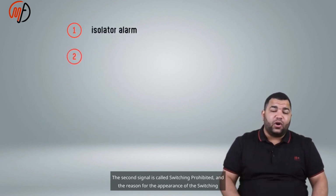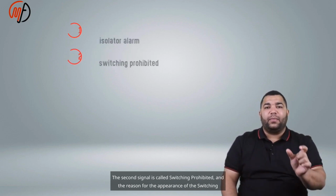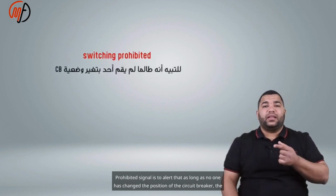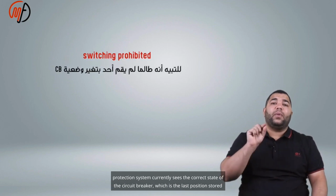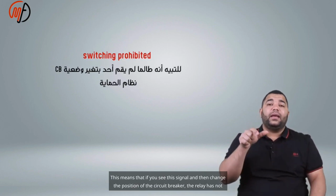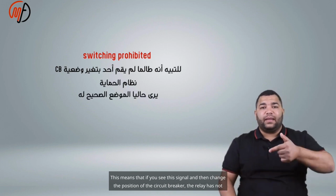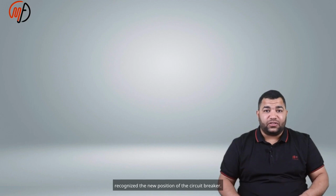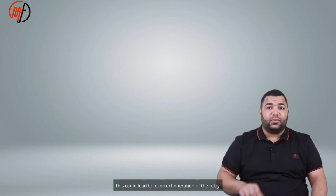The second signal is called switching prohibited, and the reason for its appearance is to alert that as long as no one has changed the position of the circuit breaker, the protection system currently sees the correct state of the circuit breaker, which is the last position stored in it. This means that if you see this signal and then change the position of the circuit breaker, the relay has not recognized the new position of the circuit breaker. This could lead to incorrect operation of the relay.